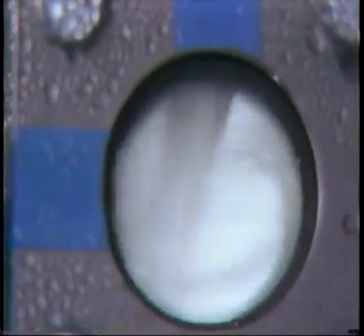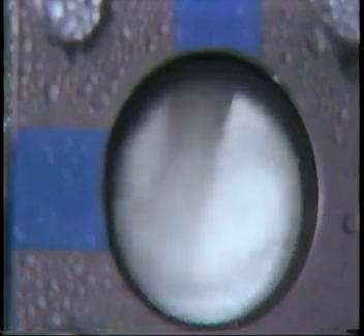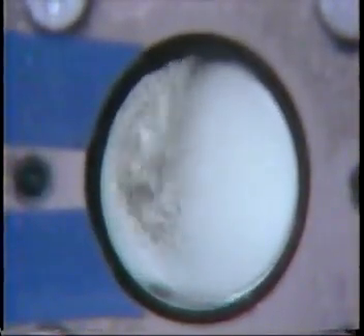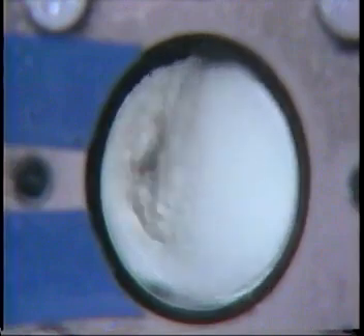When there is not enough refrigerant in the system, a greater portion of the refrigerant is a gas near the entrance to the evaporator. And most of it is a gas in the middle of the evaporator.